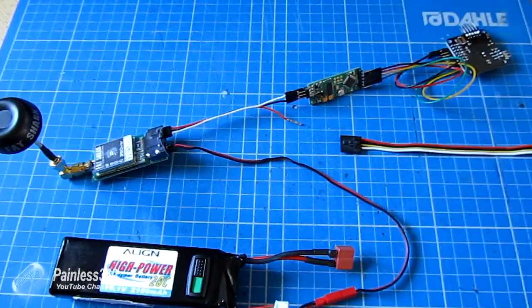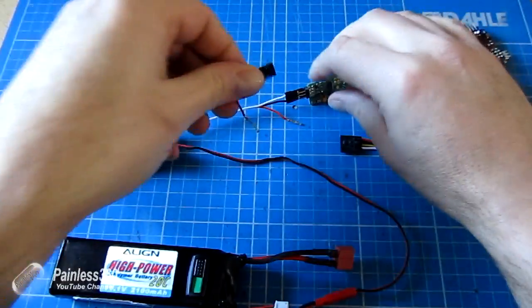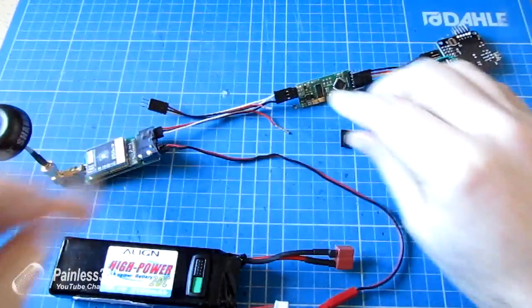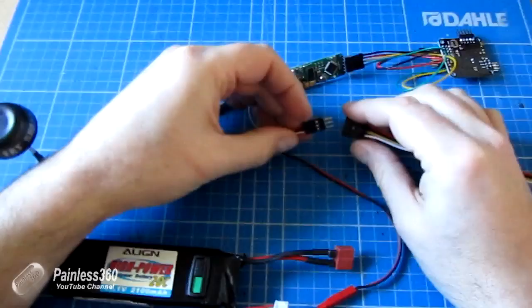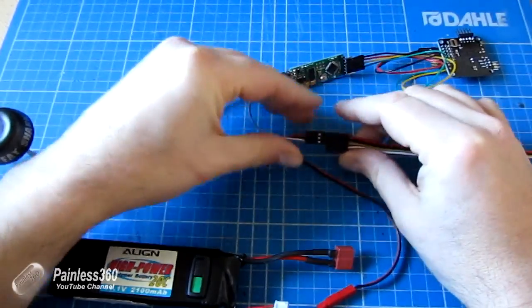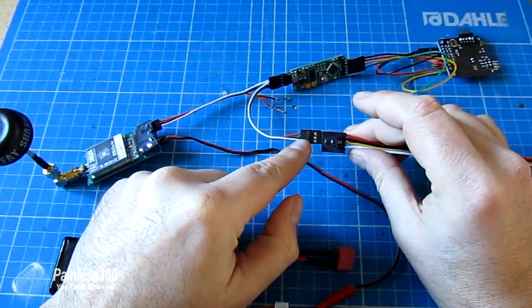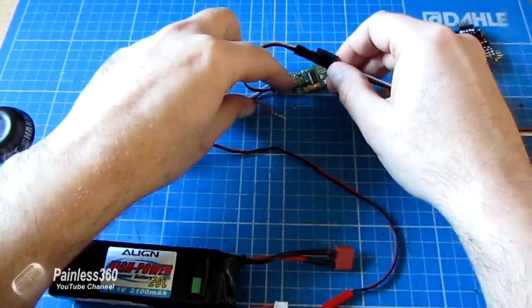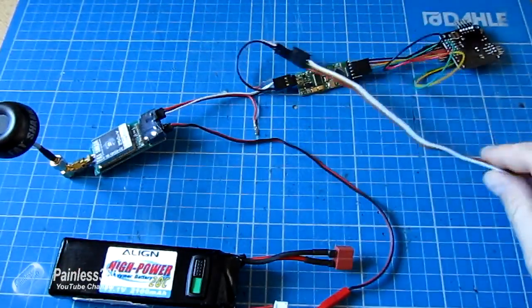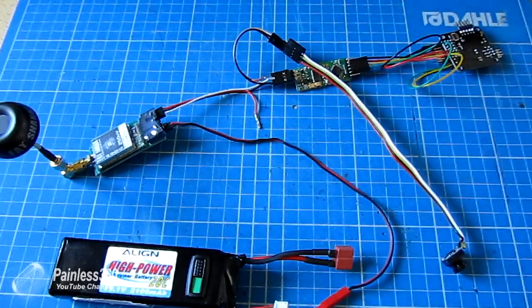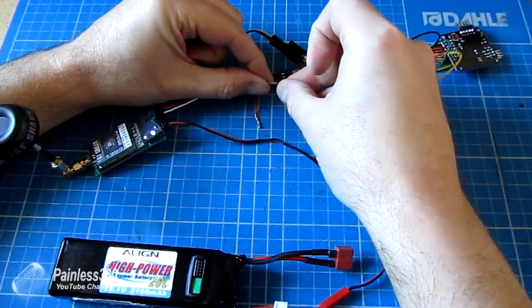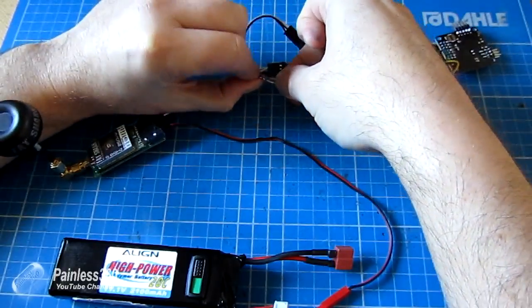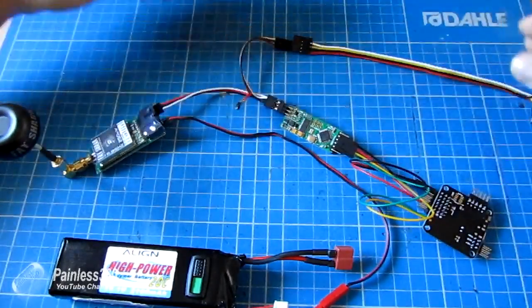Next thing we need to do is connect the video in side. So we need to connect again the negative and signal wires and then plug that into the camera, being very careful with polarity. So we're making sure that black goes to black, red to red, and keeping it the same. And then to make sure that the 5 volts can make it from the video transmitter out into the camera, we're just going to connect these two 5 volt leads together. And obviously when we install it in the craft, we'll cover this with heat shrink so that it's not going to cause any shorts. And there we are, that's it done.